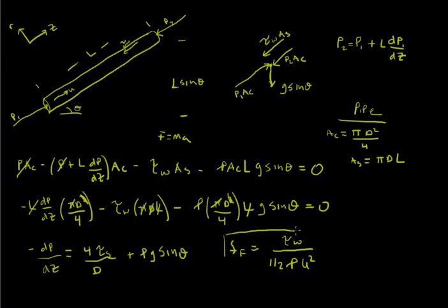So this is the definition of the Fanning friction factor. There's also a thing called a Moody friction factor, and the only difference between the Fanning and the Moody friction factor is that this turns into a 1/4, I believe, possibly a 1/8 for the Moody. I'm going to use the Fanning friction factor for all my videos here. So this is the definition that we're going to use.